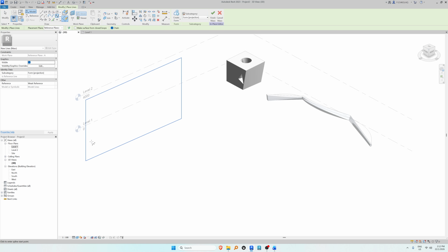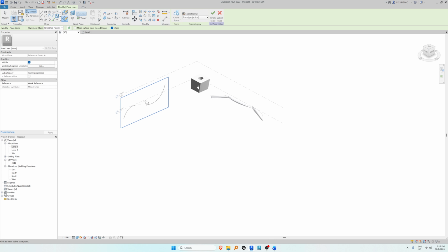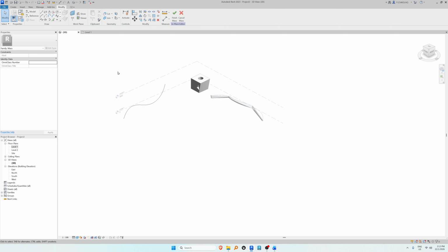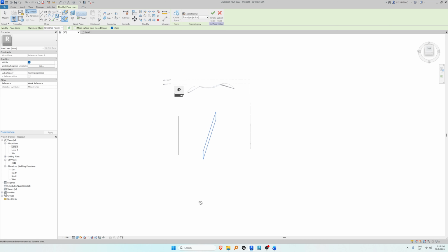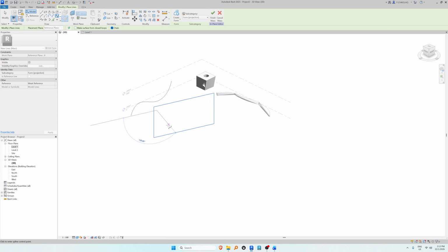Let's make a curve. So 1 time, 2, 3, 4, 5, and then press escape to exit the tool. Escape again to completely exit it. Pick the same spline tool, set the plane. This time we're going to pick B. You can see the B one, remember we had made it slanted, so B will be different.